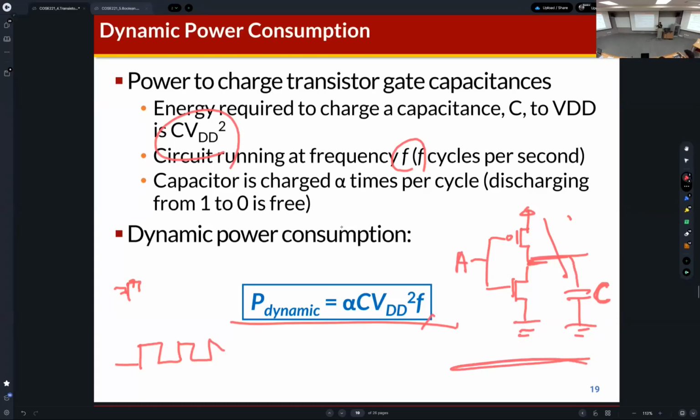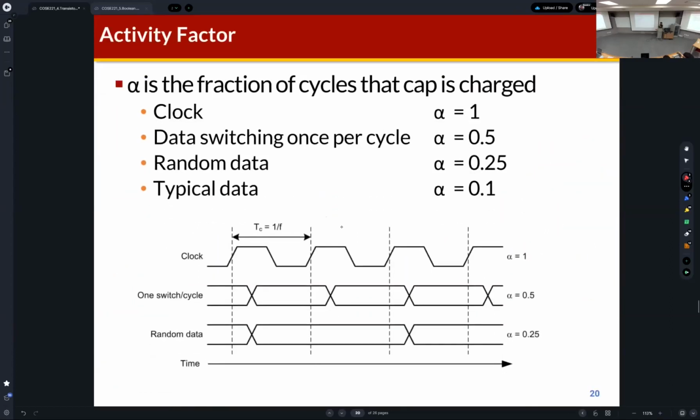Which means that if we turn on and run the digital circuit, then this digital circuit consumes dynamic power like this. And this slide shows the activity factor of the various circuits. The activity factor of the clock signal is 1. As I mentioned, the clock signal is the periodic signal that is provided to every digital component. Actually, we will learn about the clock signal in the later part of this course.